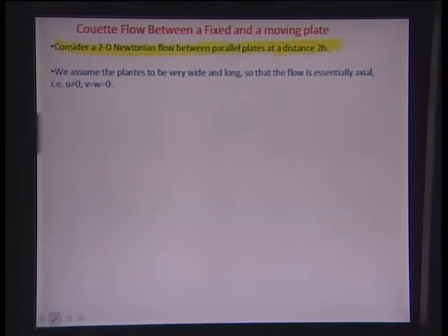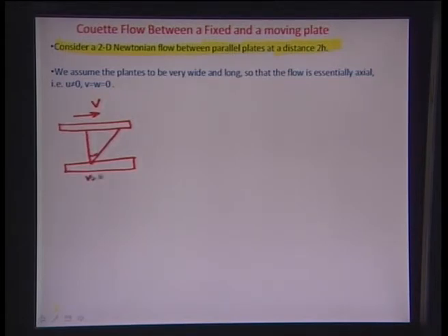Okay. So, let us draw this out. You have two surfaces, surface 1 and 2, and you have a fluid in between, and what you are doing is you are trying to move this surface at a velocity v. Assuming there is a no slip zone, the fluid develops a velocity profile starting from v equal to 0 here, all the way to about u.